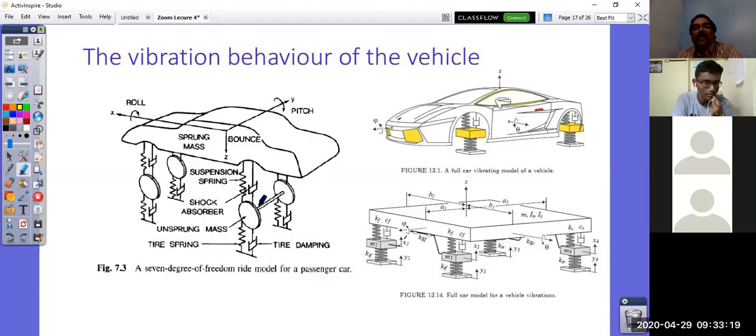No, lumped masses now, see in this model, how many lumped masses are there? 1, 2, 3, 4. Correct. So the total mass or weight of the vehicle is now discretized as sprung mass and unsprung mass of the left-hand side front wheel, right wheel, like that. So 1, 2, 3, 4. These are 4 lumped masses connected by springs and dampers to regulate your model with elasticity, right? Yes, understood.